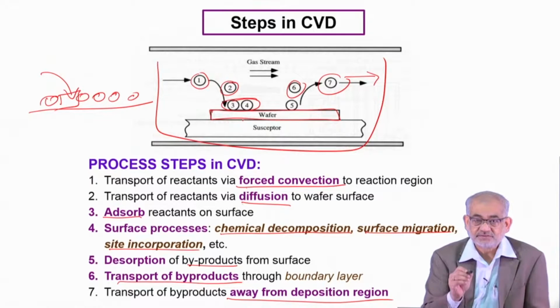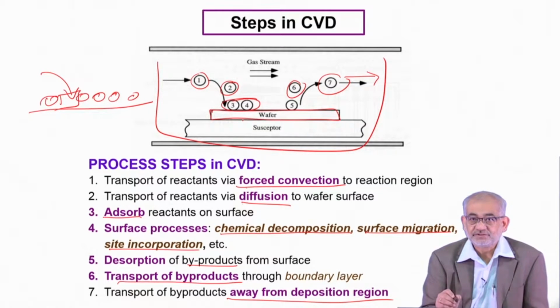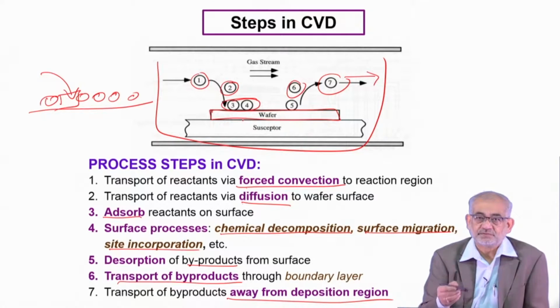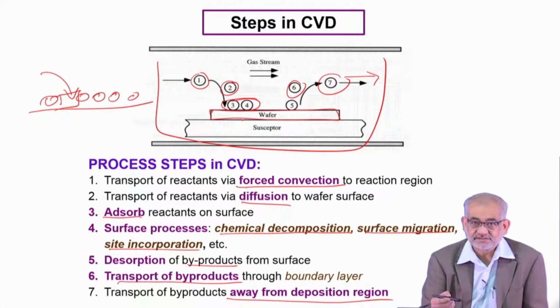In fact, always remember that the coating that we develop here, since it's very thin, there are 2 things very important. One is that the surface topography has to be fairly smooth, not rough. And number 2, the adherence with the substrate should be very strong, so that we don't lose the coating that we develop. And because composition-wise this coating is fairly different from the substrate, the interface is supposed to be fairly sharp, and that can lead to decohesion. So we need good surface integration.